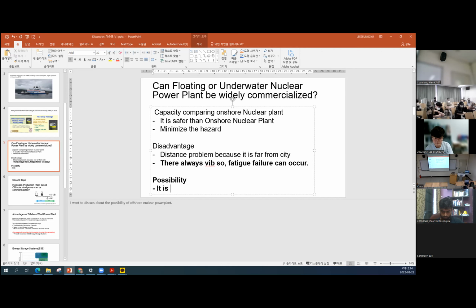Kyuhyun talked about vibrations or fatigue failure, but I also did some research and read that a lot of structures are being designed so that the natural period of the structure itself is smaller than the wave period of, for example, a tide or a strong tsunami, and larger than a peak storm wave period.